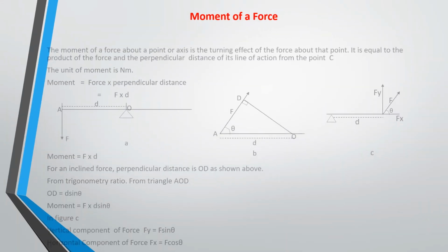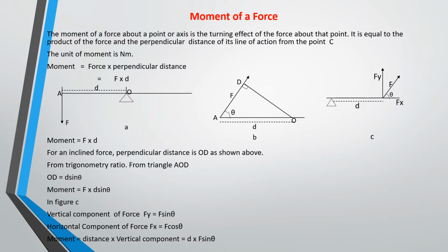So, moment of a force. What is the moment of a force? The moment of a force about a point is the turning effect of the force about that point. Okay, so it is the turning effect of the force about the point, and it is equal to the product of the force and the perpendicular distance of its line of action from the point.